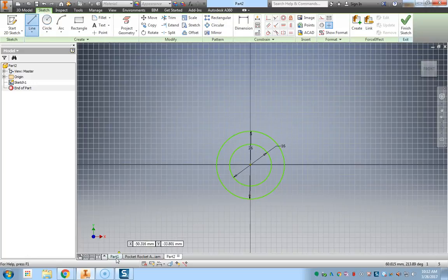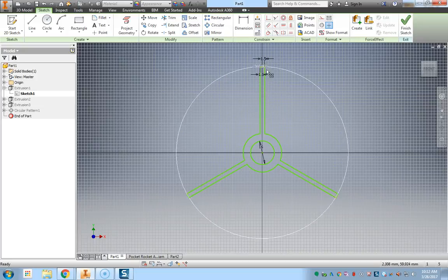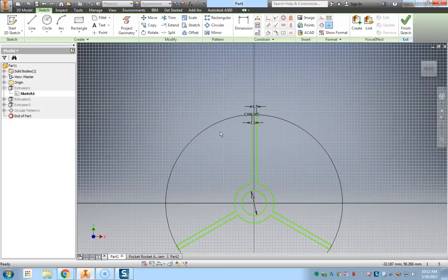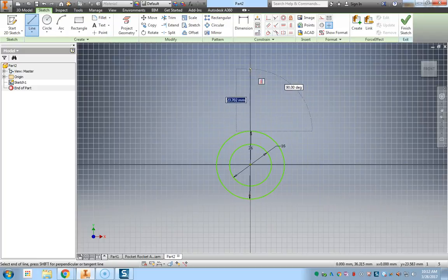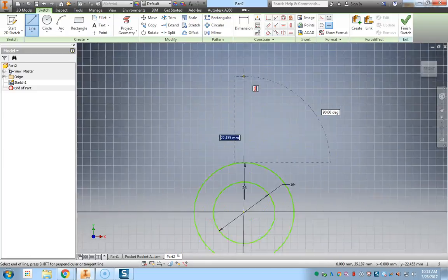At this point let's come out and draw the next part. If I go back to part 1 to look, I'm going to be measuring up 45 from here, and then over 1.5 down, and then over 1.5 down to create the first fin. Oh, I don't want to close that out. All right, so take the line, come straight down, and you notice that when I drag the line from that point up, you can zoom in, zoom out using the mouse wheel.